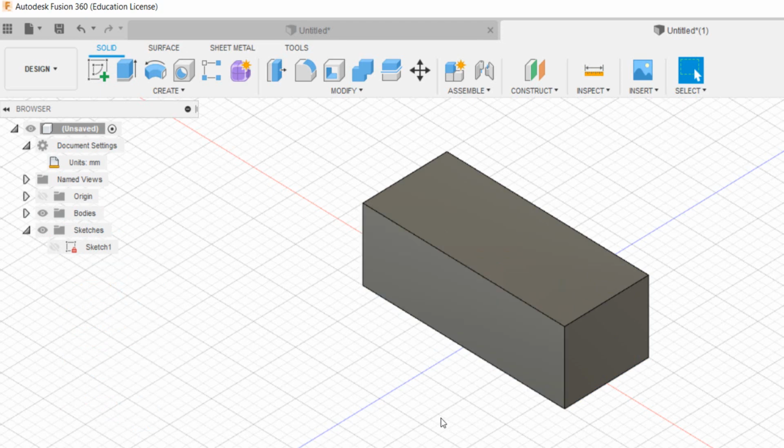Now let us say you want to apply a Boolean operation like subtraction, addition, or intersection on this model. How can you perform it? Let us see. In CAD language, we generally know all these Boolean operations by the terms join, cut and intersect. There is an option of creating a hole directly on your feature, but let us do it by using a circle and again by using the extrude command, so you will learn how the cut and join operations are performed.